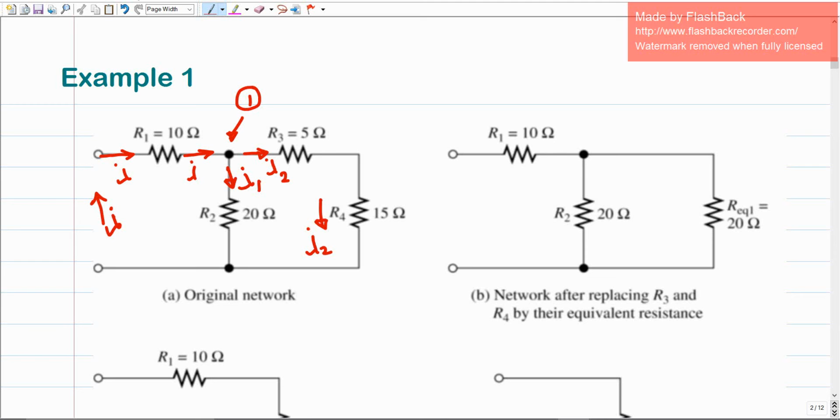So if I ask you, which resistances among all of these 4 resistors have the same current, that you are pretty sure in this configuration have the same current? Definitely, as you look at it, you're going to find that R3 and R4 have the same current, right? So what does it mean according to the definition of resistance, whether they are parallel or series? You're going to realize that R3 and R4 should be series resistors. Why are they series? Because they have the same current.